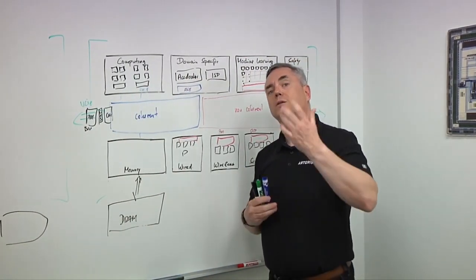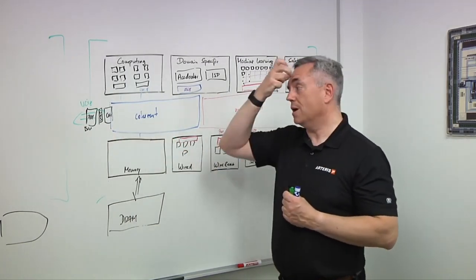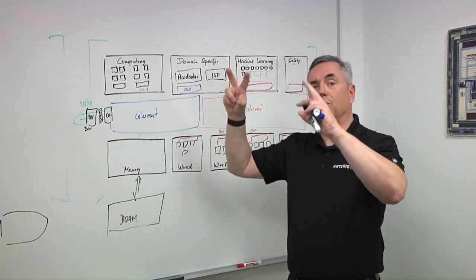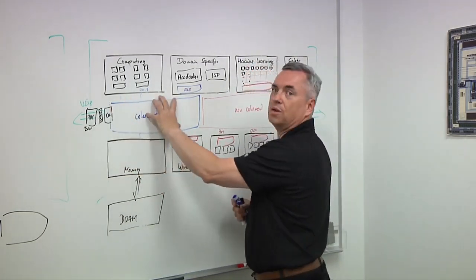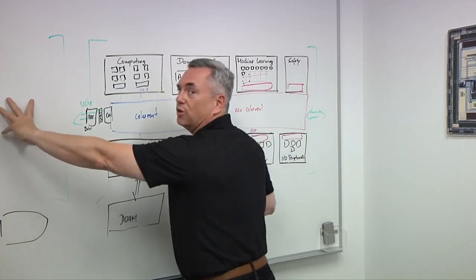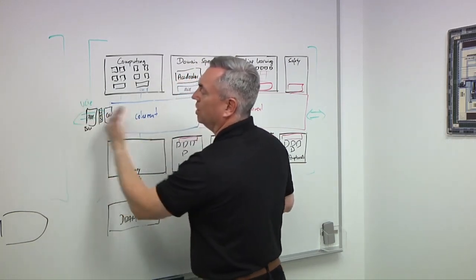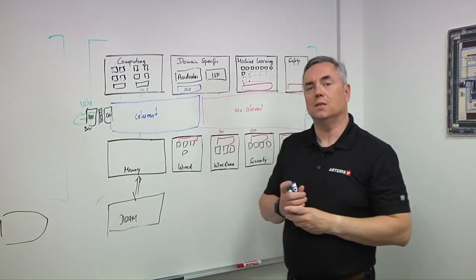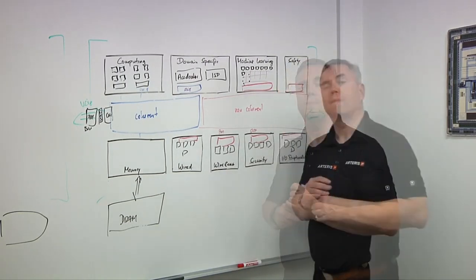So it needs to be architected right at the system level. For us as a NOC, it becomes kind of super NOCs, right? Because you now need to decide this NOC here, I have to have a flipped version here to talk over this, and you need to take into account the latencies, the bandwidth, and so forth from a systemic architecture level.